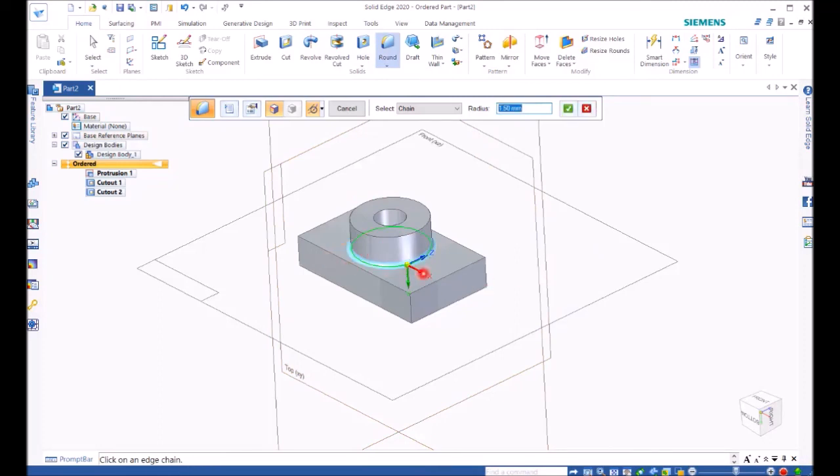The reason for that is because whatever way you machine it, it's not possible to have a sharp corner at the edge like this. There's no tool that can help you do that. Therefore, normally we have an internal corner like this, but for an external corner we use a chamfer. Okay, that's done. Okay, finish.